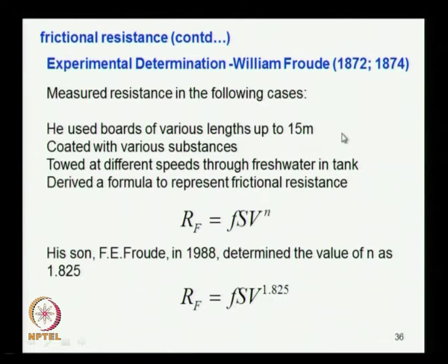When the plate is sufficiently submerged, the wave-making effect is negligible. So only frictional resistance is coming. The plate is 2D, so there is no form resistance coming there.